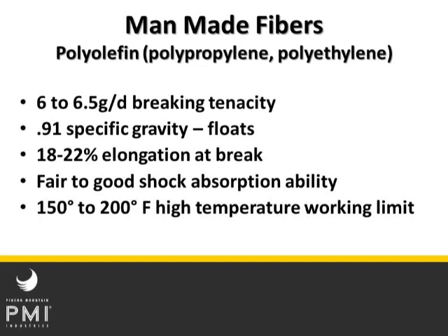So it's a good choice if you want some elongation and you need something that floats and you don't need a lot of strength. The big thing that I have a problem with in most applications is this temperature limit. It's pretty low, 150 to 200 degrees. If you try to rappel with it or do something like that, you're just probably going to melt right through it, or certainly melt the heck out of the rope in a rappelling device or something at 150 degrees. It'd be easy to ruin the rope pretty fast. It's inexpensive.